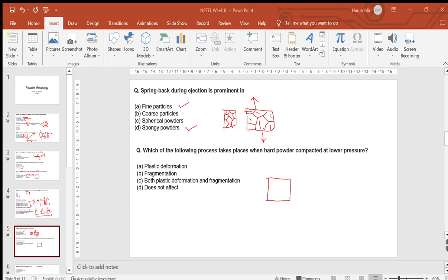You are just letting it flow in a mold, so there is no use of organic binder, but there could be a leakage of the molds inside a highly pressurized vessel. Especially if you are fabricating hollow types of parts, leakage will be a problem. So these are the advantages and disadvantages of your CIP process.